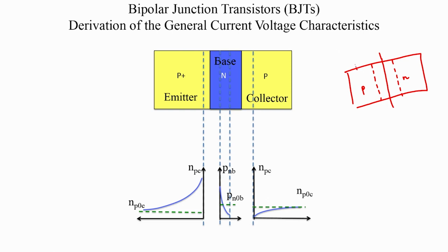We saw that when we forward biased this diode, or when we applied any voltage VA, whether it is forward or reverse bias, we had holes diffusing through, okay. So, let us say forward bias, we had holes diffusing through, and you had this excess minority carriers coming into the N side, right. So, we had an equilibrium population of holes on the N side, and that stands for the equilibrium value, that was our notation.